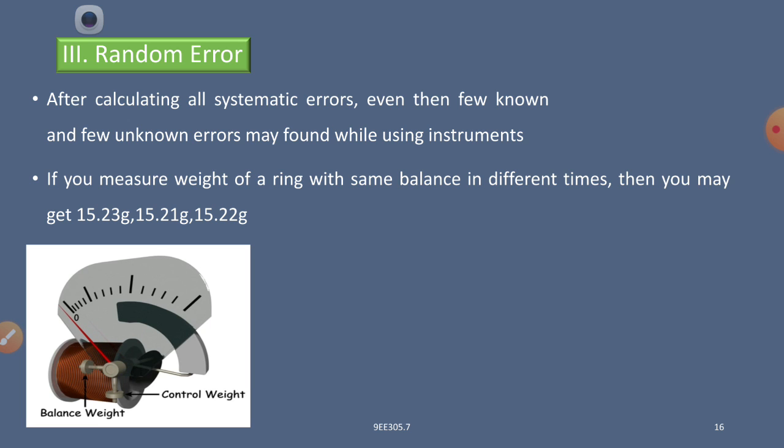Now you can see here the random errors. Error may occur here in our instrument, which is a moving coil instrument. Here the air friction damping is used. After usage of air friction, wear and tear takes place in the piston head and cylinder. The suction and pressure developed in the air friction may not be equal; it may deteriorate. Then the controlling torque decreases. Or, we have the copper coil on the armature.